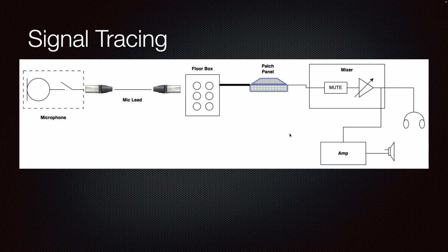And some of it you can actually check straight away. So for example, that microphone's not working. Are you sure that these things at this end, in terms of the mixer and the amp, are working? So if you played music from maybe another channel, does that come out of the amplifier and the speakers? Is the amplifier actually on, for example?